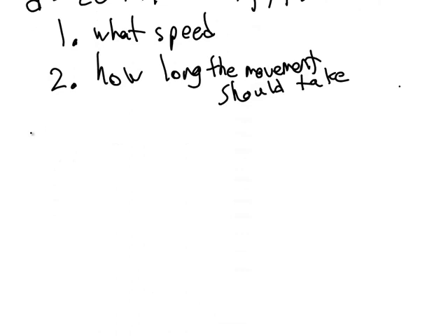First of all, let's suppose that we're going to set a limit on the speed of the motor. Now note that in open loop control, we're going to set a constant speed for the motor. In the future, using other kinds of control, we might vary the speed during the move. But here, for the case of open loop control, we're going to keep the speed constant. So in this example, let's suppose that I want the motor to move no more than a velocity of 100 millimeters per second.